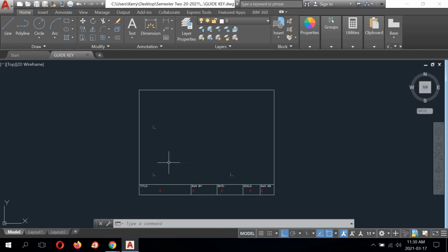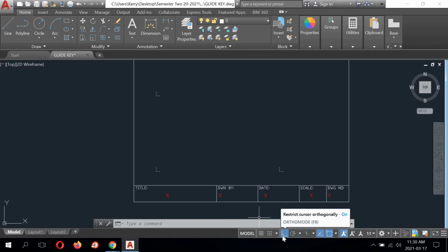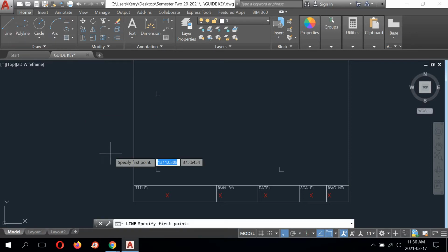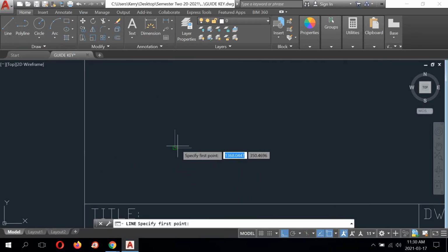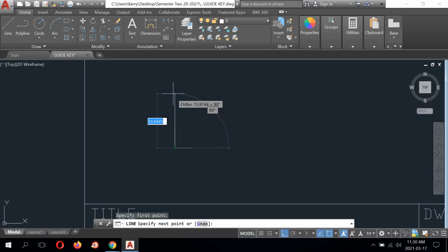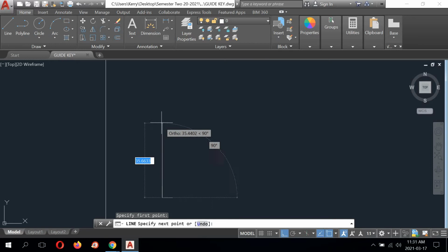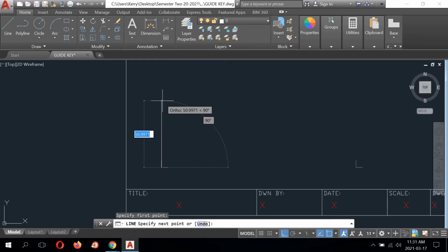I am going to start, I believe, with the front view. So ortho is already running. I'm going to go and get line from the draw tools. Zoom in with my wheel, find my endpoint, snap at my usual starting location, left click, pan out so I can see more clearly, key in my height, which is listed as 51.5.